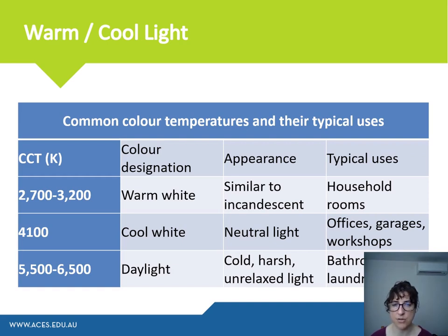Generally they'll be put in the bedrooms, and they'll be considered sometimes in lighting design. It's usually when people put up the new fast builds, like where they're building a block of units and they're not really thinking too much about how someone's going to use a house. They're just getting them up to make money. Then sometimes you can have the entire house with 4,000 Kelvin LED, just bright lights everywhere, including the bedrooms, because they haven't really thought about it, and that's really going to be disruptive to people trying to sleep at night.